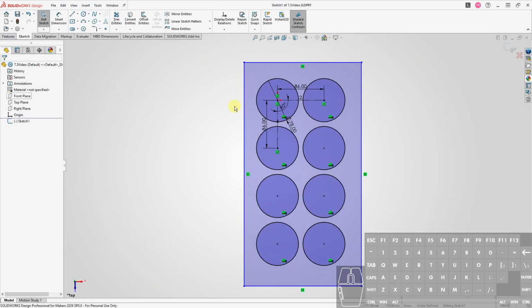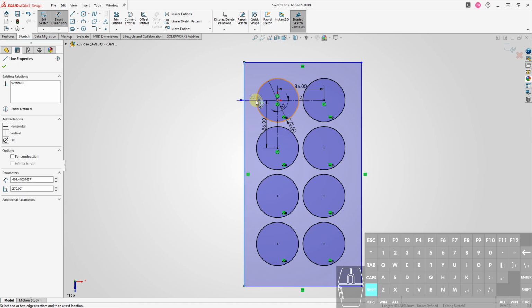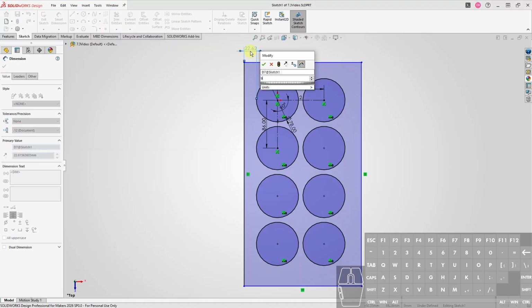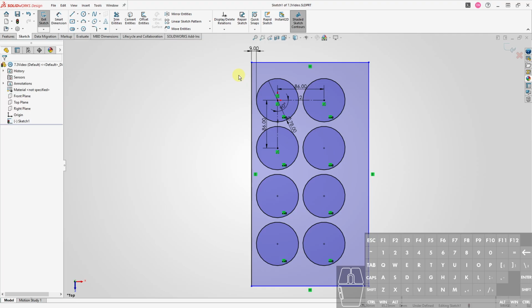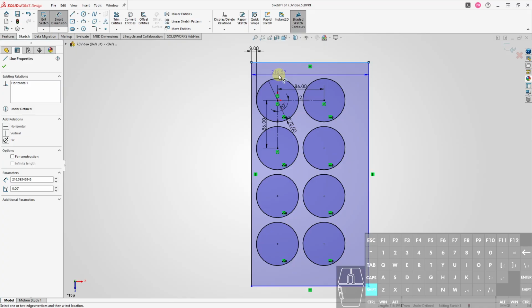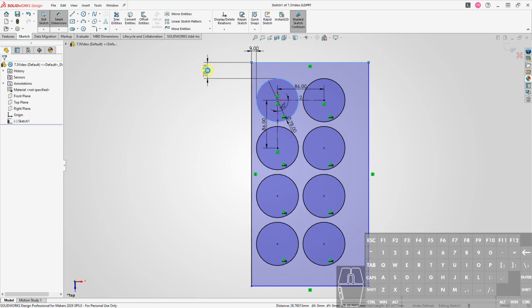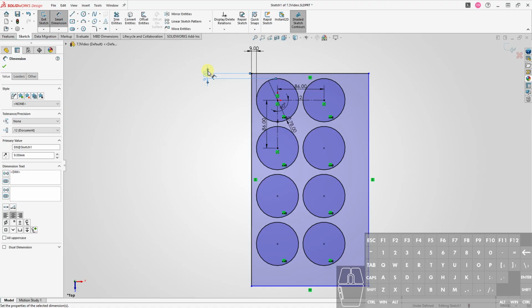Okay, so remember when you're adding a dimension to the edge of a circle, you have to hold down Shift and then click. So that's going to be 9. So I'll go into dimensioning, click on this line, Shift click, and you have to hold down the Shift, otherwise, oh, actually I did, I guess you don't, never mind. Okay, so we got 9 here.